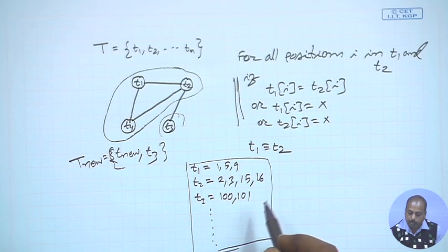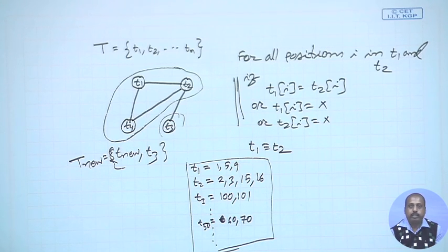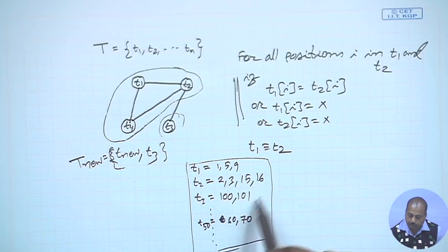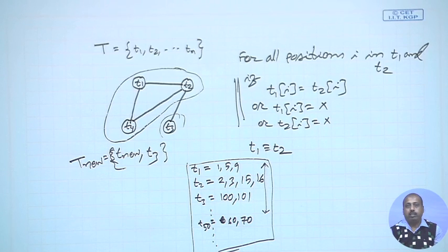But you see that any pattern, say T50, has detected some faults, say 60 and 70. These are 2 faults detected by this pattern. But the point is that at this point of time, all the faults that have been detected by the previous patterns have been dropped from the set of faults.